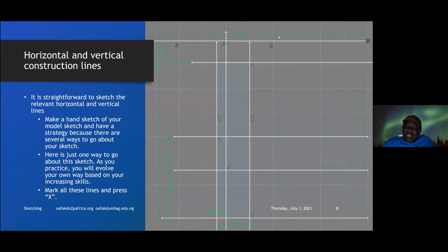If you study that drawing very well, you will see that we need to draw 1, 2, 3, 4. It is a good idea to draw these horizontal lines and then to draw these vertical lines. Don't mind me, this line should be longer, at least should meet at this point or longer than that. So it's a mistake that this line ended before this line. It should be. So provided from the origin, you draw the first line at 32, and then you make sure that the distance between it and the next one is 2, and then the next one is 7 away from here.